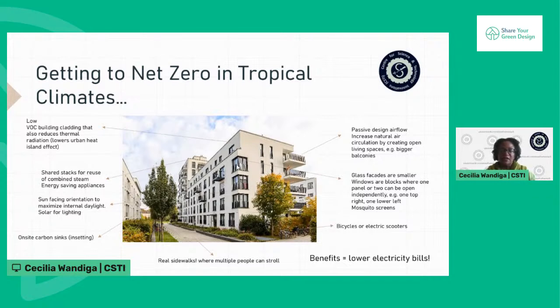The facades here, you see that instead of having a large window like this that would take up the whole facade, you make smaller windows, and probably if you can have each one of these panels here become workable panes, then you can decide, depending on the airflow that day, how to open this one and the lower one and keep these two closed, and give the end user consumer some more ability to have maximum type of climate control without having to trigger air conditioning systems.